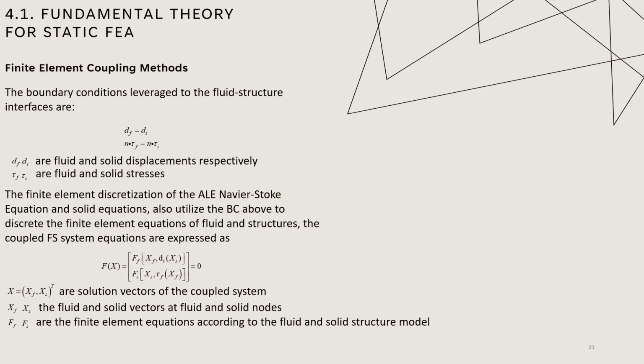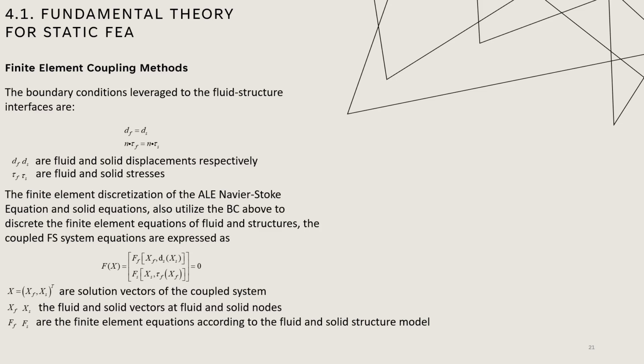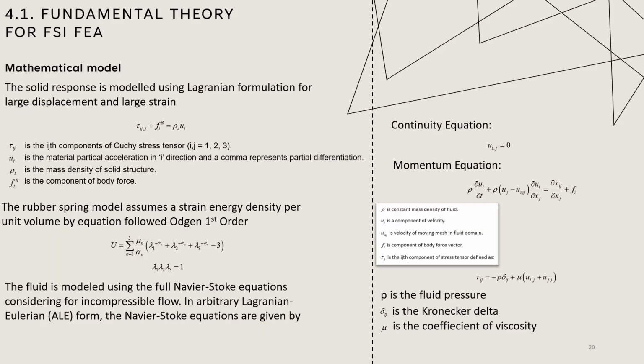For the fundamental theory for fluid-solid interaction FEA, I'm sorry, I forgot to change the word static to FSI. So for FSI, you're gonna take a look at the mathematical model. So for the solid response, we're gonna use the Lagrangian formulation for large displacement and large strain.